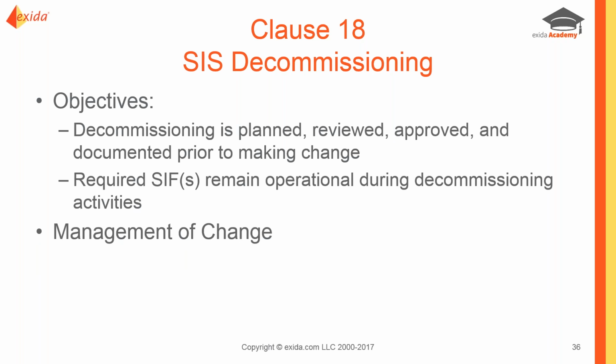Same thing is true for the decommissioning phase. We go back through management of change, make sure that everything remains operational during those decommissioning activities. And the two main reasons we may have decommissioning activities would be retiring one system to go into a new one, doing an upgrade, or if we've had change in our processes that have actually changed the risk profile and we find we don't need certain SIFs anymore.